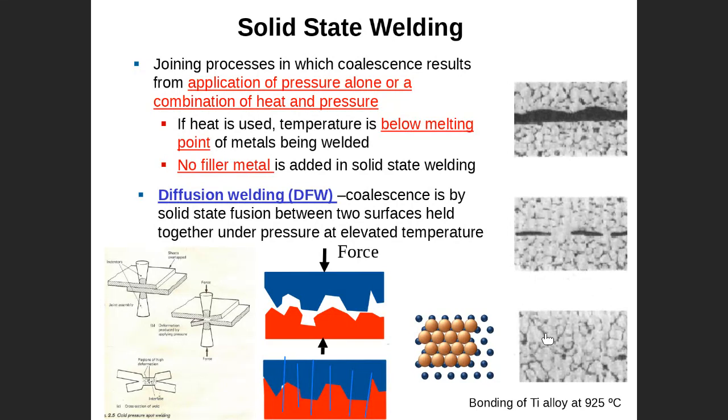Why? We don't have any problem with the heating and melting and contraction. Even if we add heat here, it is low temperature, usually lower than melting temperature, and should be fine. We just encourage the atoms to move up and down and so on, then a bond will be created and the weld will be done. Okay, let me show you a nice video